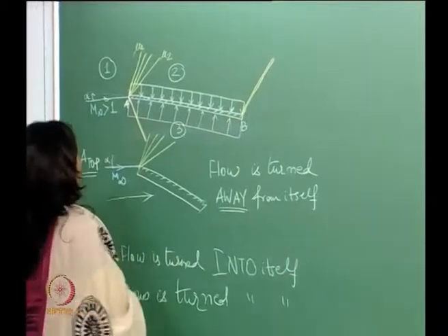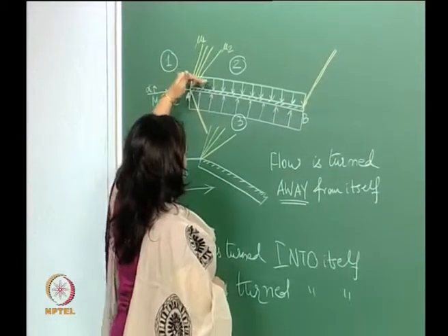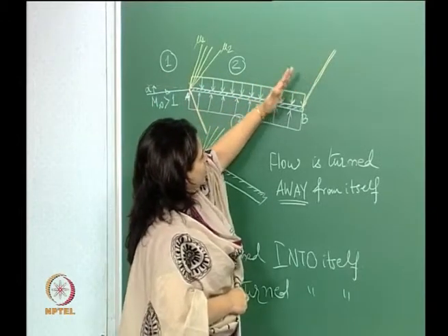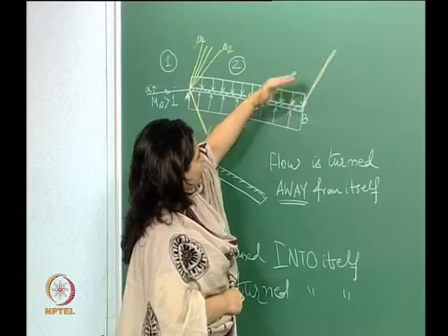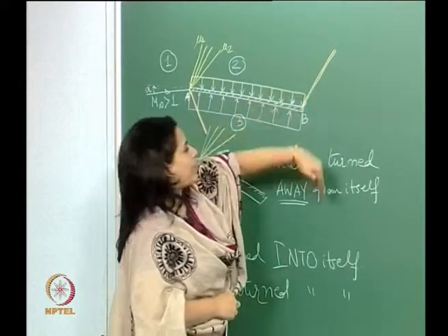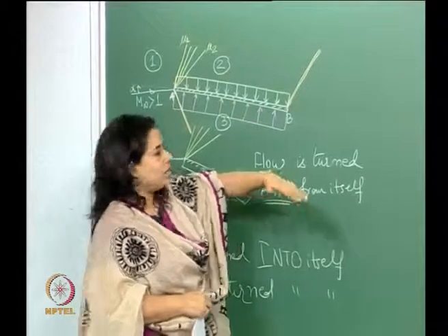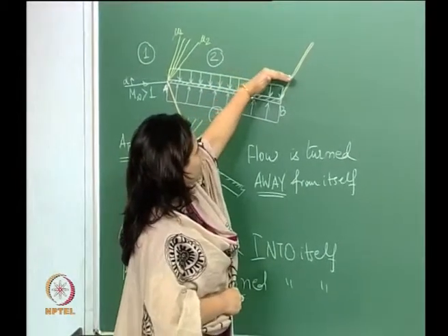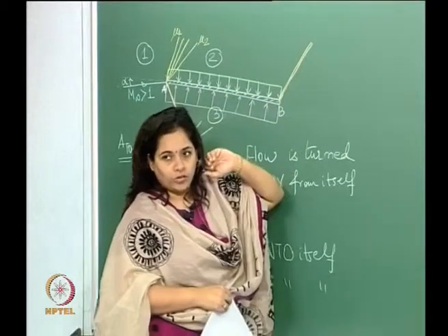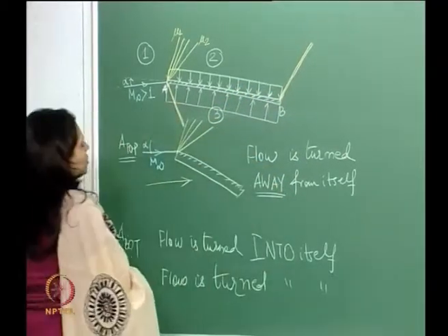If you now look at it, when the flow expands, it comes over here. Now you shock this, so with this shock it deflects and keeps following. It doesn't come and expand over here and leave it like this. It comes here, it reaches the shock, and it deflects and keeps going according to the free stream. That is what the shock does.